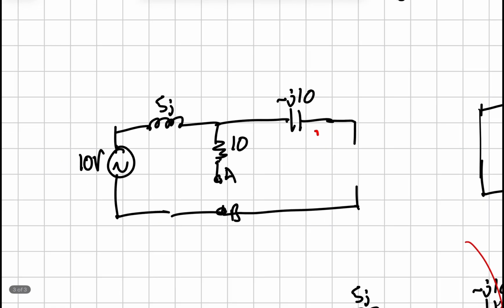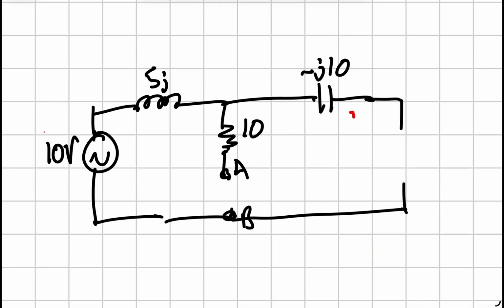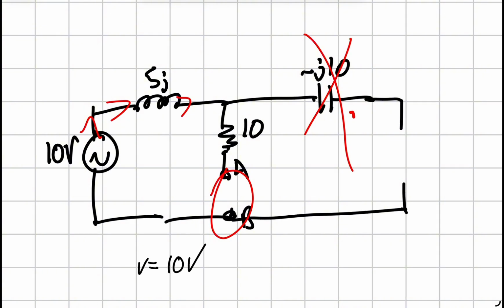Then on the voltage source, you look at the 10 volt source, and the current source is opened. You go through here and you realise there's an open branch like last time, so you'd get rid of that. But you realise there's a gap between the A and the B as well, so the voltage doesn't change. It would stay the same because there's nothing affecting it.